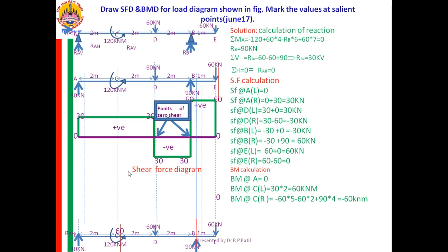Here it hits the top of AC. Therefore, the beam bends in the downward direction, so the effect of the couple on the part AC is negative. The effect of the couple on the part CE is positive. That is the dangerous part in the SFD and BMD. The couple will create the problem.